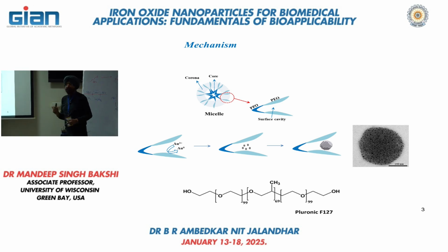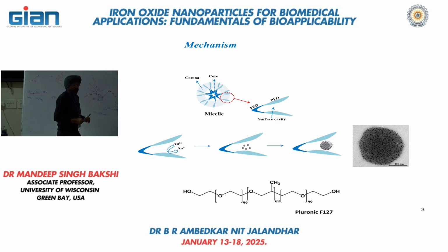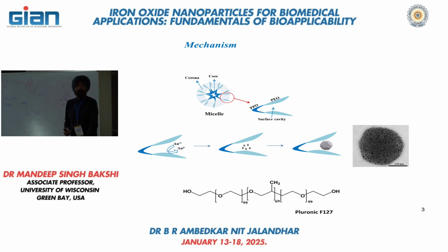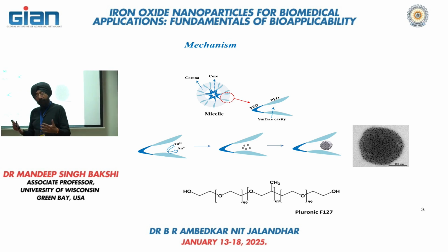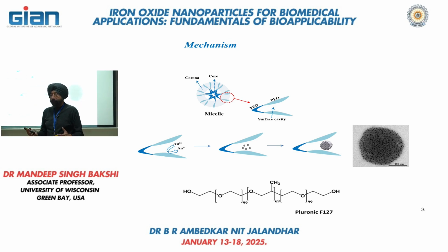So this is known as the template effect. If somebody asks you, what is the template effect? It is the way that we could put the nanoparticles, which are dispersed in the aqueous phase, aqueous suspension, can we direct them onto a specified platform? You will say yes, it is possible. You could allow the reaction to take place on a platform or on a template, so that all the nanoparticles which are going to be produced will remain on the platform, that is the aggregated state or self-assembled state of the nanoparticles. So we will talk about what is the advantage of this.